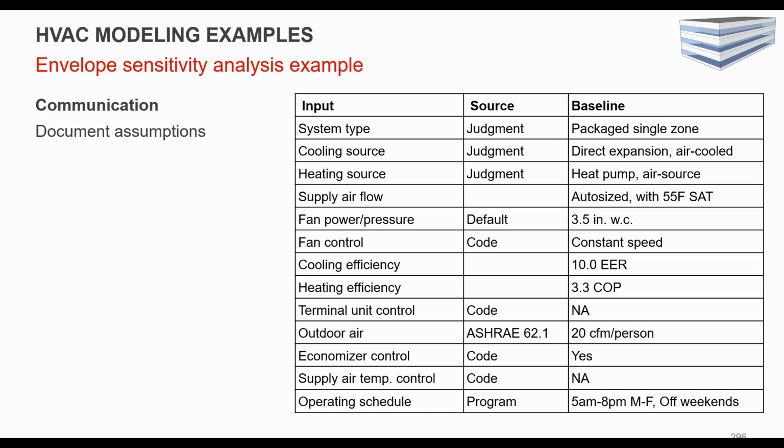And then also, the 0.12 CFM per square foot, is that standard practice for OA? That is not standard practice. I'm just saying for this specific office, that's kind of a number where we end up seeing 0.1 to 0.13 CFM a square foot for ventilation for offices. But certainly that will depend on the density of occupants and the type of space and how many different space types you have within the building.